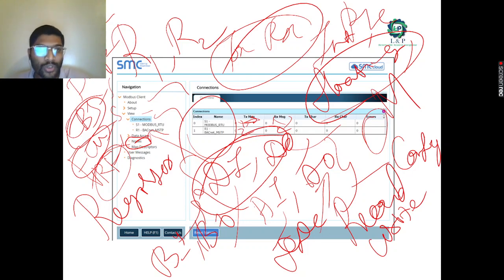So through the nodes you're going to access as a master. It will act as a master. You're going to access the different slaves with the different slave IDs. Then you're going to assign some read memory, or holding registers. So through the holding registers or the IDs that you have assigned, you're going to assign them through the object ID or the BACnet ID that you have assigned in the field, that is going to be the slave ID. With the help of the object instances, you're trying to read them, and you're collecting all this information in the data arrays that you have created. From there, you're moving that information to the PLCs.